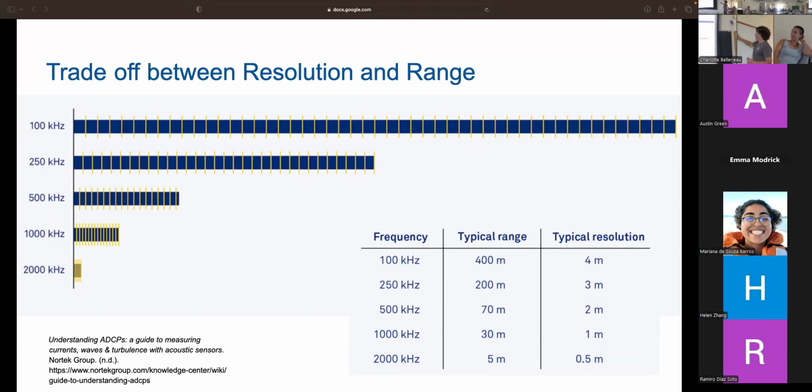here, actually. A common thing that you'll see is what we call a coded pulse. It's basically some repeating value that we tune that should not exist in the ocean in any form. So how we actually do these measurements is we spit this out. There'll be a series of a few of these in a row. In the project I use, we have 7. Anyways, so we spit this out, and our bin sizes are dependent on the length of this